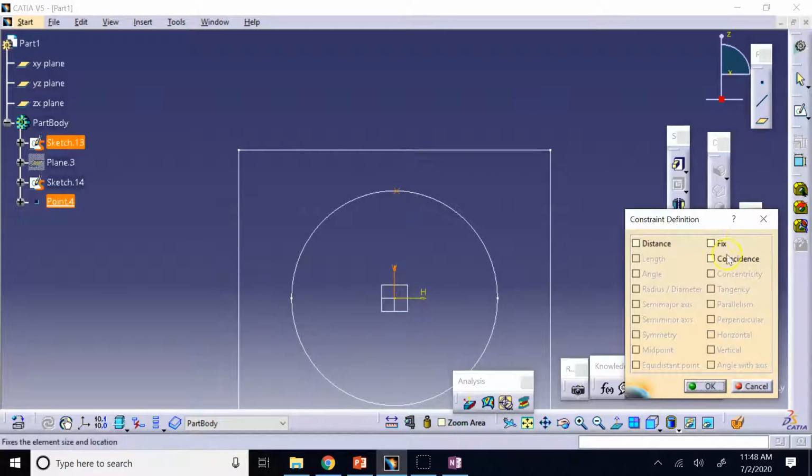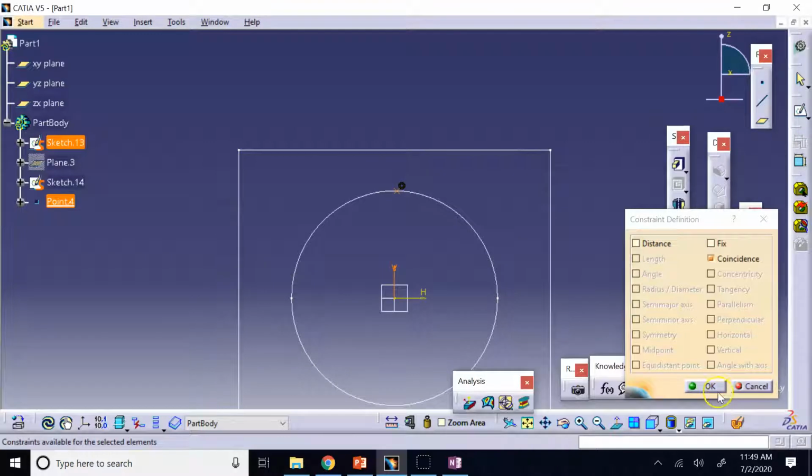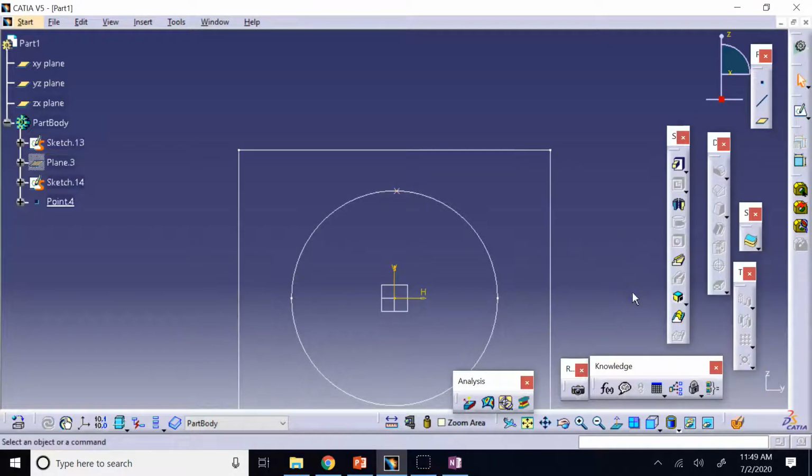We have to see here. It allows apparently coincidence, but no, it did give an error. Why? Because they are not even on the same plane. So you have to make sure that the point that you create is exactly above the v-axis. So just providing a number of length and ratio is not going to ensure that.